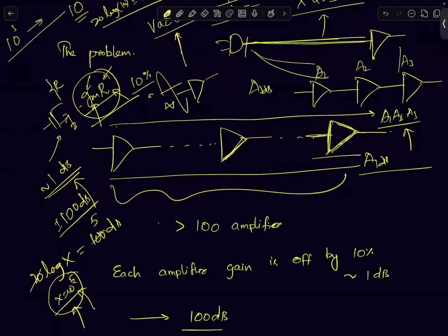When you over amplify your signal, you end up saturating the amplifiers. When you saturate amplifiers, they become nonlinear. When your amplifiers become nonlinear, then you don't hear the speech signals accurately. So that's one problem, and this was a big issue. What was needed when Harold Black was working on this was to come up with a way of designing amplifiers whose gains were relatively constant.